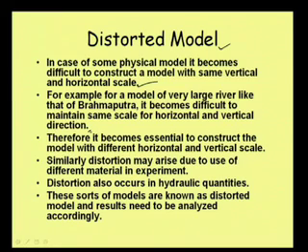So how do we do this? We construct the horizontal scale different and the vertical scale different, and that makes the model distorted. Distorted means we are not maintaining the same scale in the horizontal and vertical direction. Well, then there may be another case.